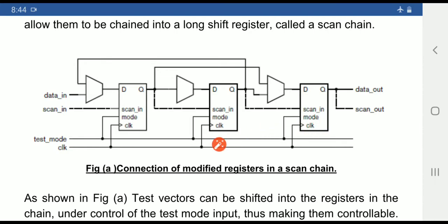If the expected result matches the outputs of each flip-flop, then we can say that the output of each flip-flop is correct. If there is any variation or difference in the outputs, then it allows us to detect that there are faulty outputs in the flip-flops.